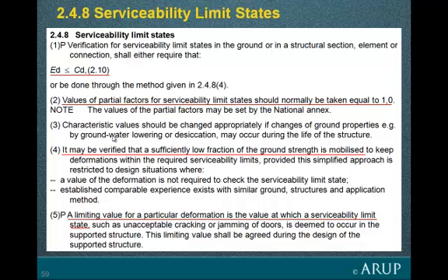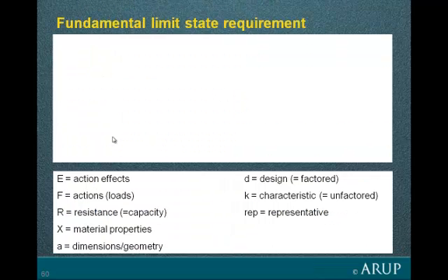As an alternative to calculating deformations as such, you may verify that a sufficiently low fraction of the ground strength is mobilized. So this is looking at mobilization factors, if you like. For these types of calculations, various Oasys programs are available. PDISP, often used for calculation of settlement, XDISP for settlements around excavations, FREW for movements of retaining walls, ALP for displacements of piles, or SAFE, general finite element analysis, for settlements, movements of retaining walls, and so on, a whole range of possibilities with finite elements.